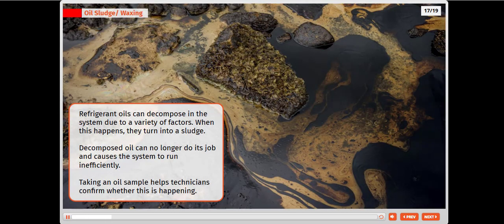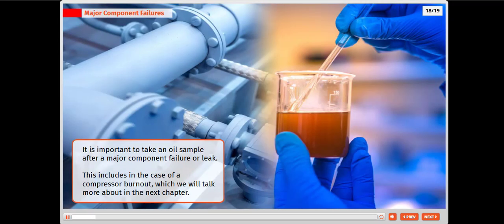Refrigerant oils can decompose in the system due to a variety of factors. When this happens, they turn into a sludge. Decomposed oil can no longer do its job and causes the system to run inefficiently. Taking an oil sample helps technicians confirm whether this is happening. It is important to take an oil sample after a major component failure or leak. This includes the case of a compressor burnout, which we will talk more about in the next chapter.